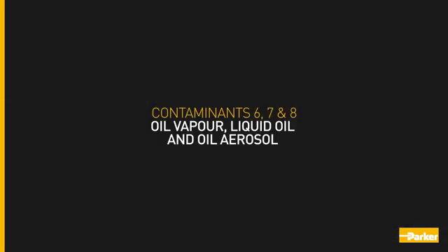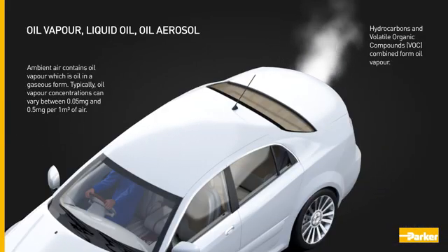Contaminants 6, 7 and 8: oil vapour, liquid oil and oil aerosol. Ambient air contains oil vapour, which is oil in a gaseous form. Typically, oil vapour concentrations can vary between 0.05 milligrams and 0.5 milligrams per cubic metre of air.